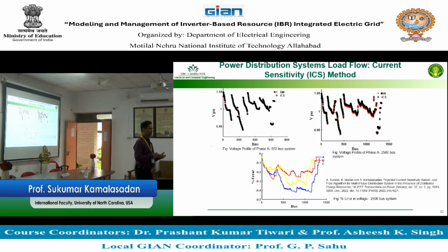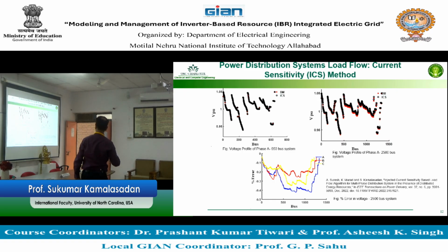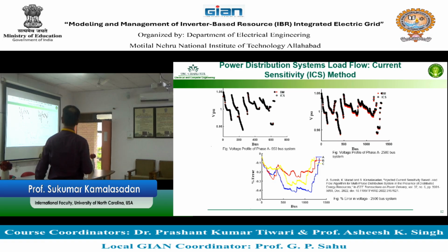We also talked about scalability studies, testing. So you can do that on this graph. So you can see percentage error. You will look at what is the percentage error between each phase. Oh, by the way, when you plot the voltages on an electric distribution system, you will have to plot it for every phase and see that phase voltages are matching, because there are unbalances. So that's a challenge on an electric distribution system.